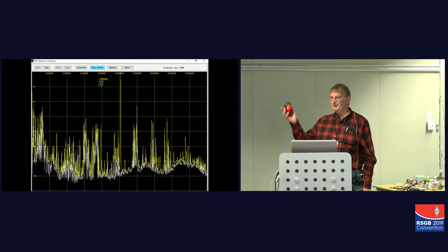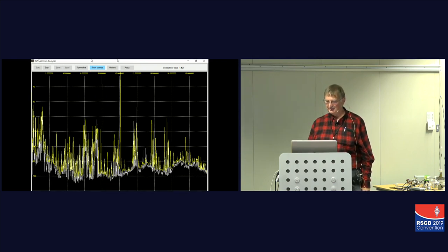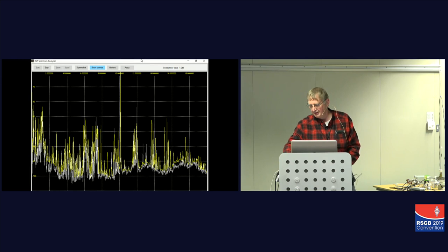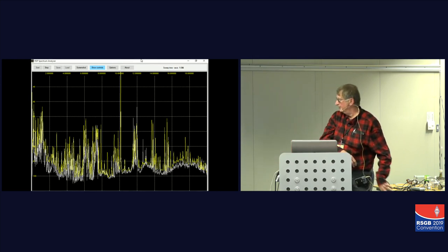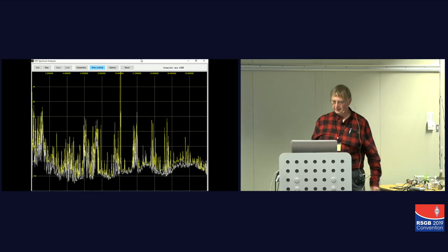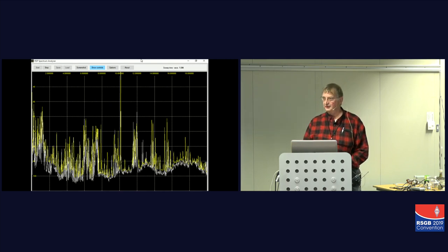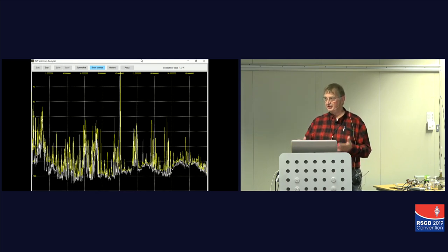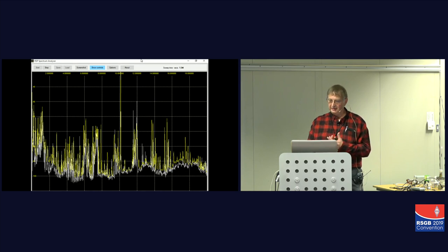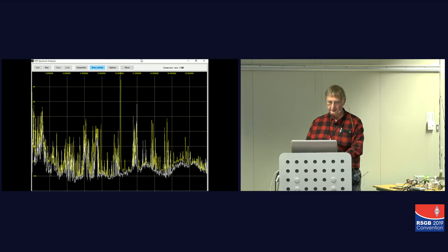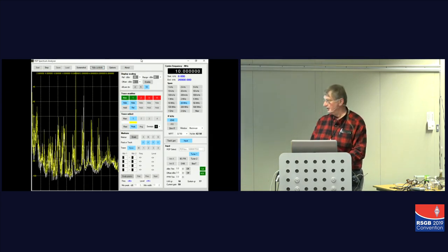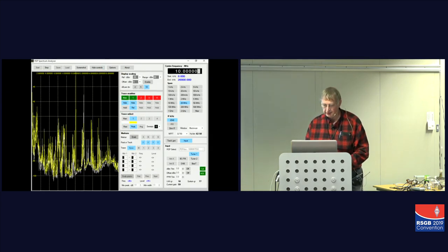So what am I using today? A mouse. Also, currently, I'm running with the power supply in. If I take it out, you will find that the level of interference will drop. So I stressed battery operated. I'm now stressing, make sure that you understand your test setup before you go any further. Get back on the right screen. Put the slideshow back on again.